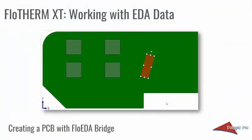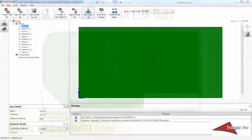Electronic systems invariably involve a printed circuit board or PCB, or simply a board. The thermal model of the PCB may need to be manually created in the thermal design environment or imported via the IDF format, or a more detailed format such as ODB++ or Mentor Expedition. FloTHERM XT supports the EDA workflow through the FloEDA Bridge. Let's take a look at these workflows, beginning with the Creating a PCB example.